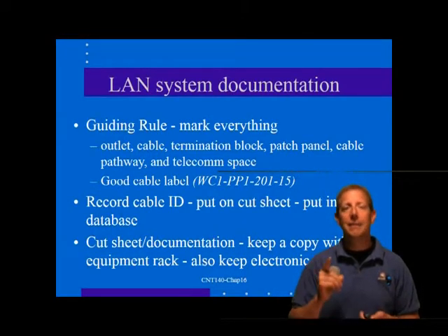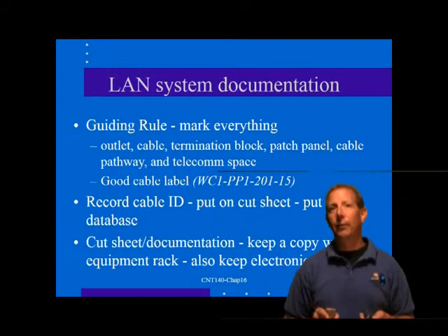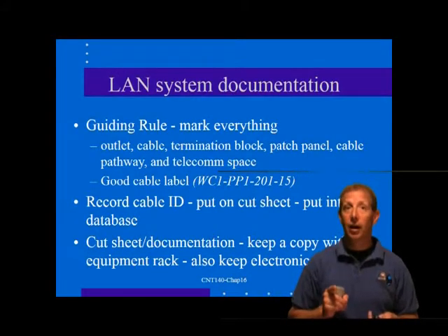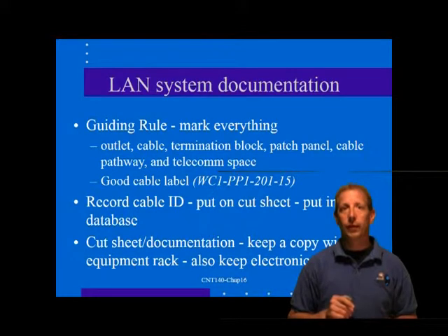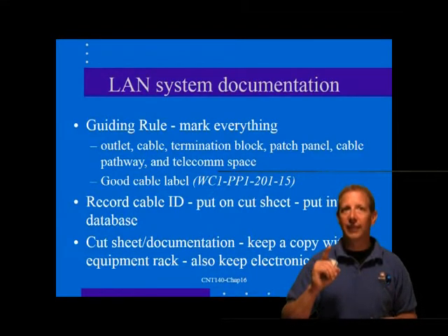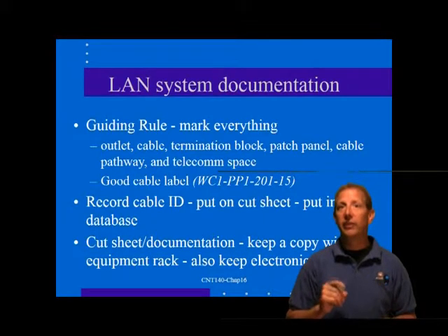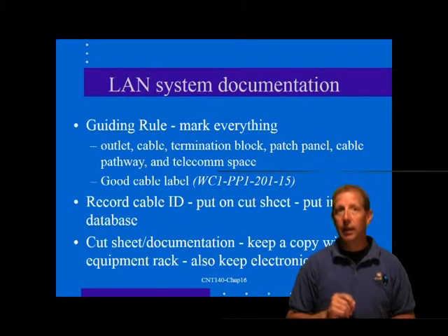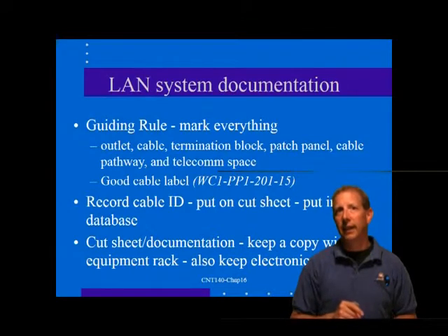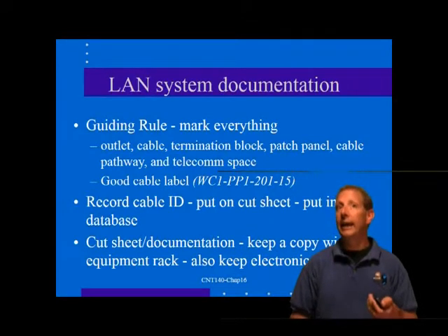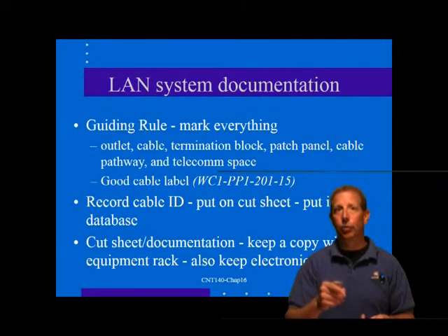As a matter of fact, many of the mounting structures and pathways that are used to support LAN wiring are best identified as well. LAN documentation standard TIA/EIA-606-A. In an effort to standardize the administration of telecommunication cabling, the TIA published this document, Administration Standard for Commercial Telecommunications Infrastructure. This standard covers the identification, nomenclature, and documentation of wiring, pathways, and grounding and bonding in commercial buildings.